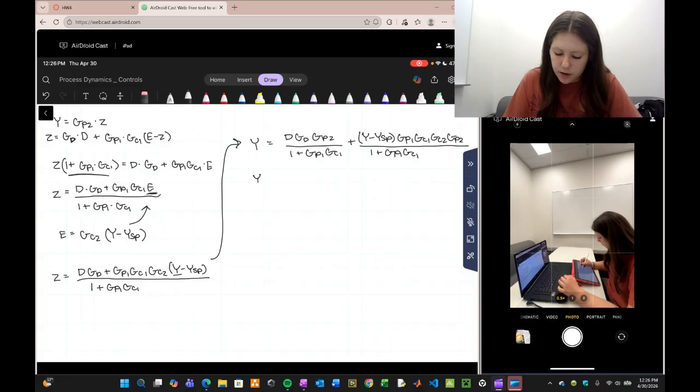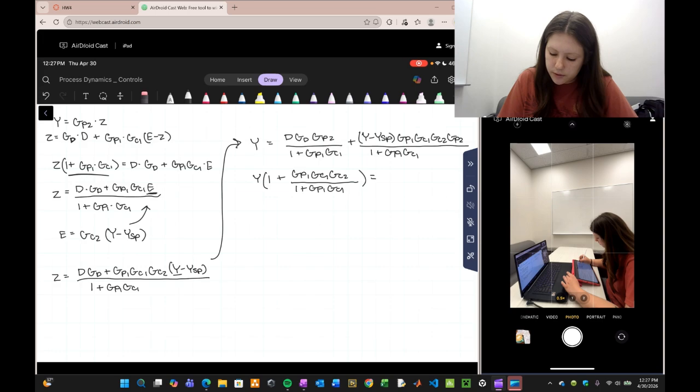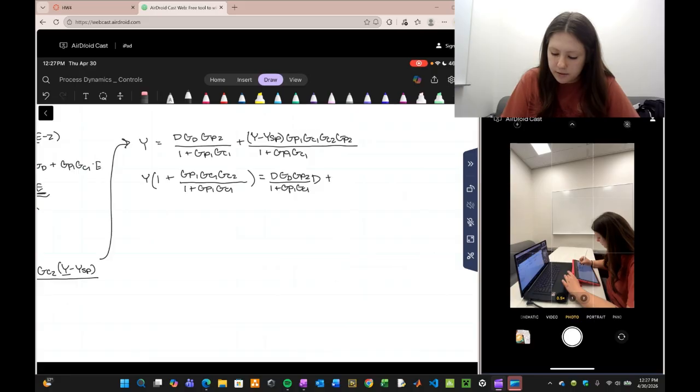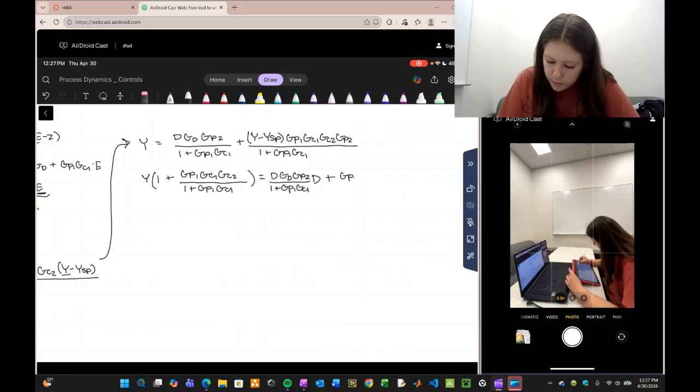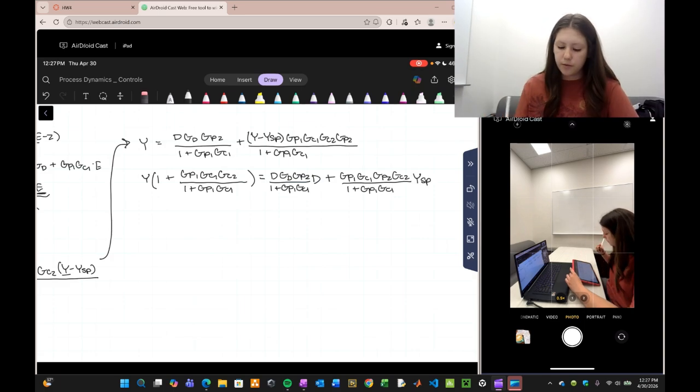So then we get Y times 1 plus GP1 GC1 GC2 over 1 plus GP1 GC1 equals D GD GP2 over 1 plus GP1 GC1 times D, and then plus GP1 GC1 GP2 GC2 over 1 plus GP1 GC1, and then that will be multiplied by our set point of Y.